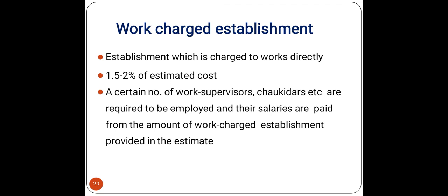Next is the work charged establishment. Establishment which is charged to works directly is known as work charge establishment. It is almost around 1.5 to 2 percent of estimated cost. A certain number of work supervisors, chowkidars, etc. are required to be employed, and their salaries are paid from the amount of work charge establishment provided in the estimate.